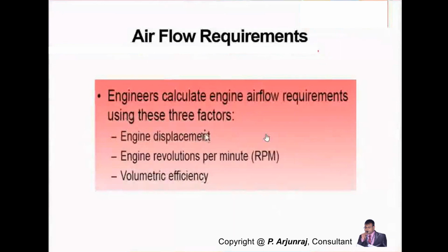One is the engine displacement, the displacement of the engine, and then the engine revolution based on the RPM, and also the volumetric efficiency. These three factors are very important to calculate the engine airflow requirements.